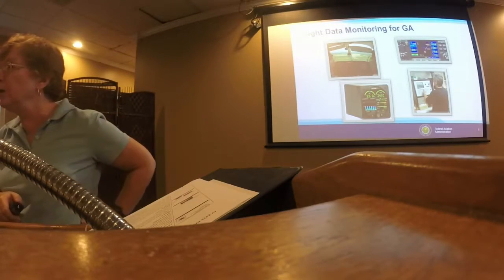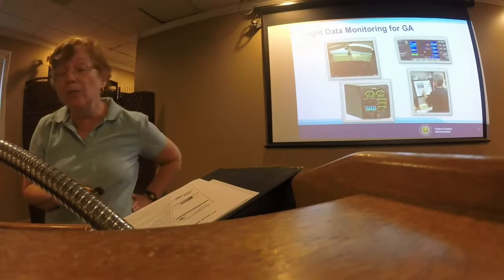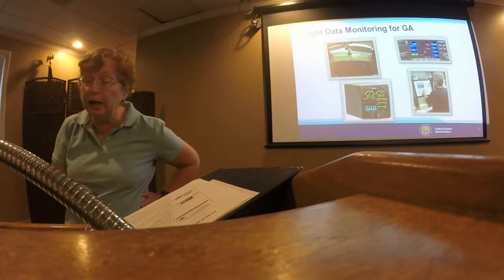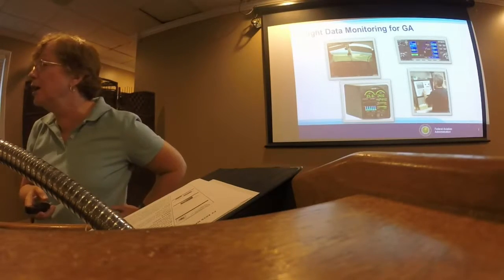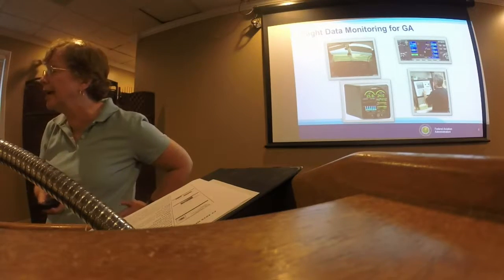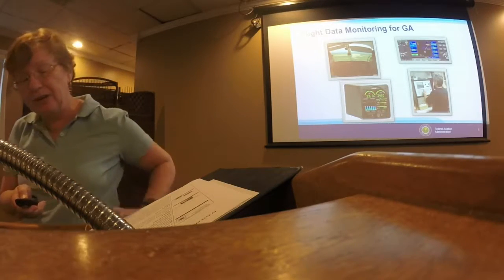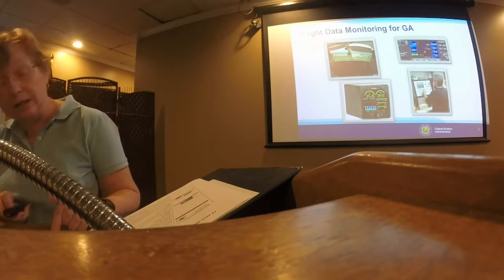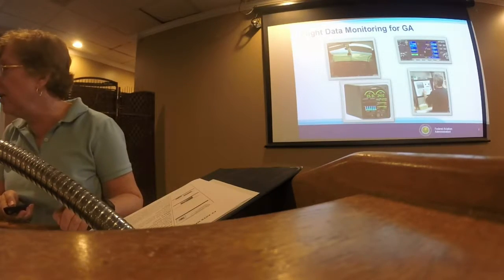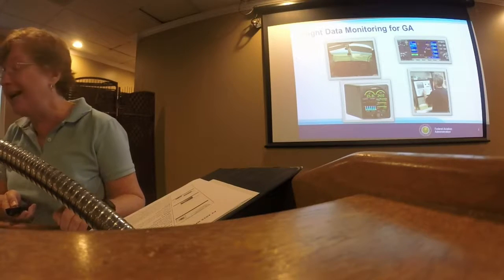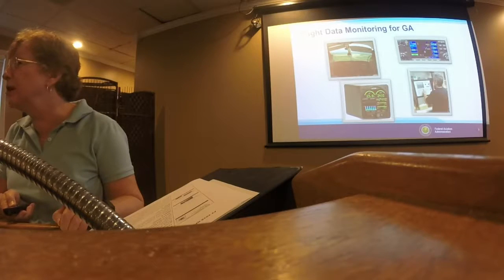Now, other people are doing things such as oil analysis programs. Obviously, this doesn't have the granular detail of something like this, but you can definitely analyze whether or not the engine is making metal and perhaps stave off a catastrophic failure while you are flying the airplane. Some aircraft, especially helicopters, have metallic chip detectors. If they see metal, they know it's time to land now.